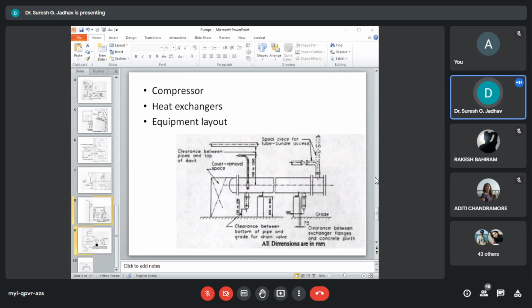High pressure and high speed compressors must have pulsation dampers to eliminate pulsation in suction and discharge piping. Pulsating flow adds stress to piping structure and process equipment. Material fatigue can occur.